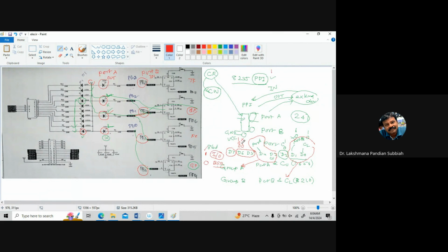Then the symbol IO mode, port A as output port, and port C whatever it is, I am just putting output now because port C is not used here. Next, the third bit: this is the symbol IO mode, and port B acts as input mode, and we have the C upper, don't worry about that one.